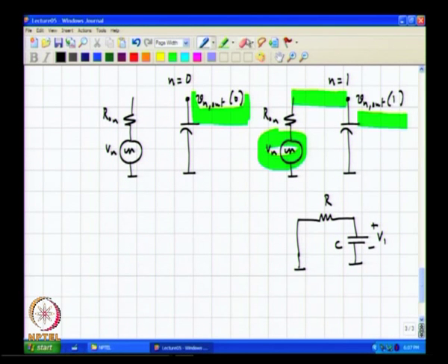Please note that will not be the case if the RC time constant is too large. If I deliberately choose the RC time constant to be very large, there are two things happening. One, V1 is decaying, and the input noise voltage is trying to charge up the capacitor. If the time constant is too large, the decaying will not happen, which means that at the end of the second clock cycle the voltage on the capacitor has some part of V1 plus something else.